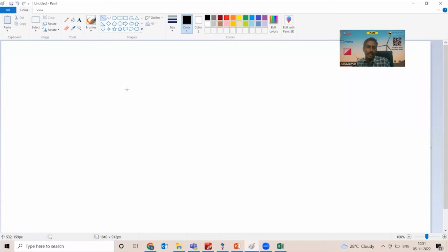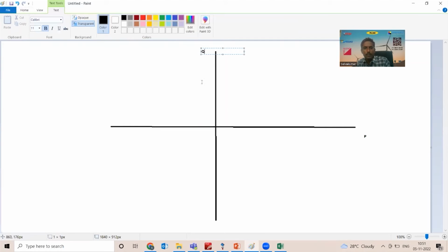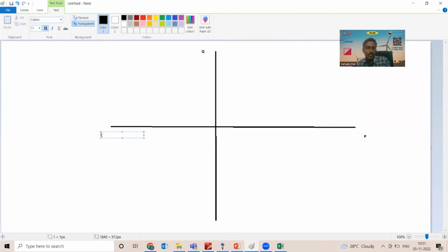Let's go to the capability curve again. If I pick a capability curve, keeping P on the x-axis and Q on the y-axis, for a generator, the generator cannot have an operating point in the negative P, right? This is negative P.